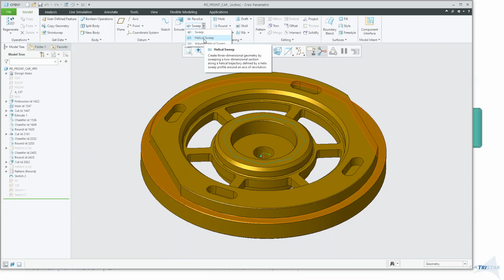So normally we say it's not a good practice because it takes regeneration time, but I see where you're coming from for 3D printing, yes, or even for analysis, FEA, you'll have to have the thread geometry. So no enhancement on the helical sweep itself, but they've improved the hole command. When you do a standard hole, let's say a 1/4-20 tapped hole, you have the ability to control that cosmetic surface, which I know may not help you, but they've controlled the depth of it. But for helical, is there anything specific you'd like to have? We could let PTC know on helical sweep, anything you're looking for, Ken?